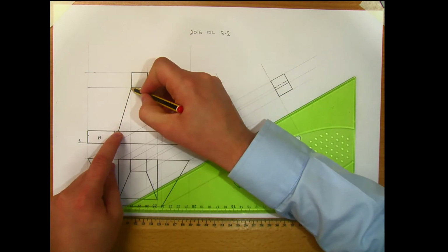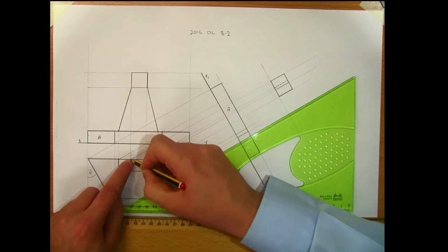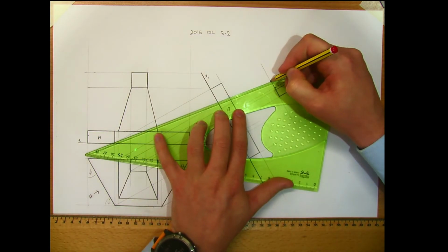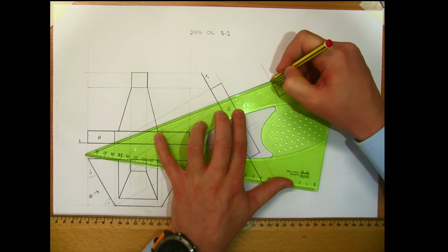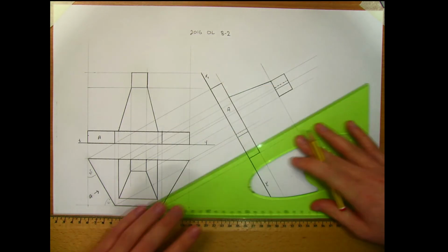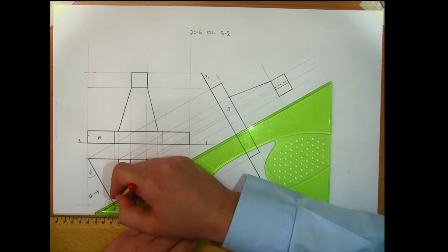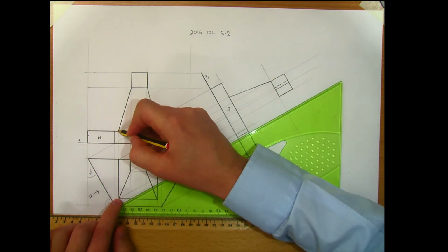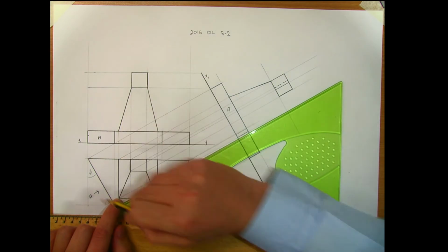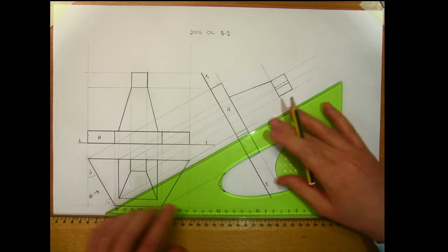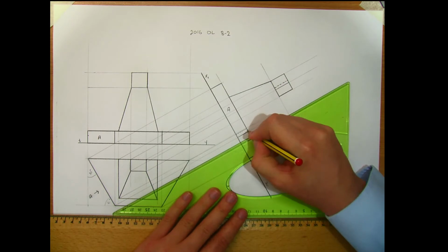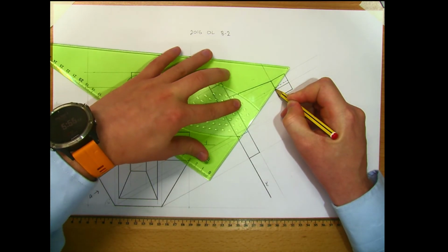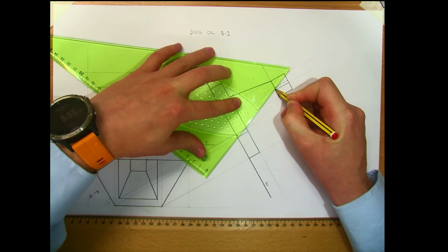That joins to this corner. So let's follow that corner down, and that joins to this one. So this corner, those two are going to join up. Gives us that one. Doing the next one here at the front, so taking this line, projecting that one up along. Again, this corner is in this position, so it's this height off the ground, off the XY line. So same position as it is here, that's this one. So I can join from here down to that line.